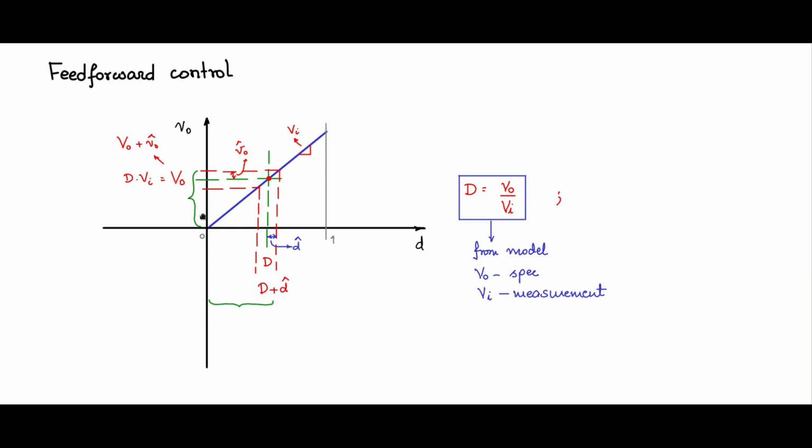So the PI controller that we discussed till now is supposed to handle all these variations, which means that the operating point can swing between 0 and the actual operating point, and the PI controller is supposed to handle these large signal variations. As opposed to this, with feed-forward control, what are we going to do? We are going to use this. We said that this is the model of the system.